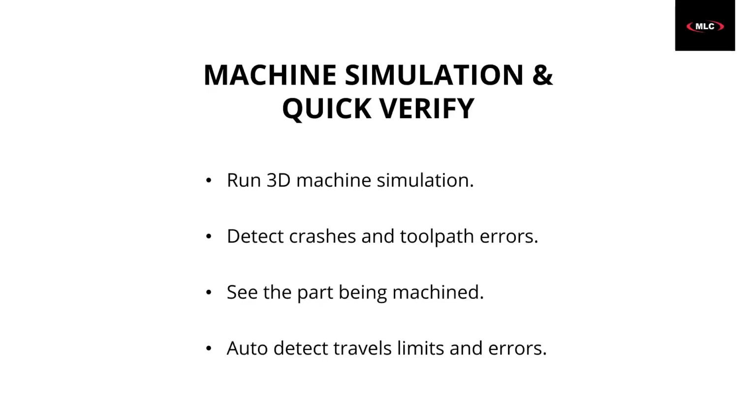So now to close the deal, from verifying NC programs, verifying our Mastercam programs in a faster, more efficient quick verify. Now we're ready to post the program, but I want to verify the posted program. I want to verify how my machine is going to run the posted program.